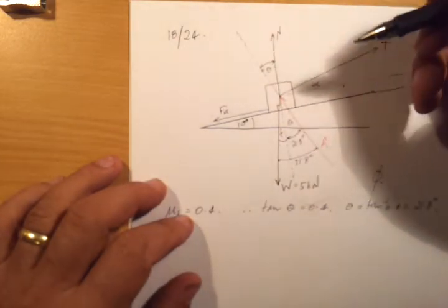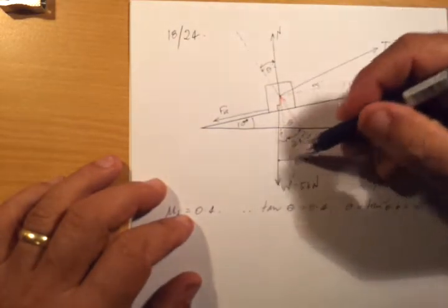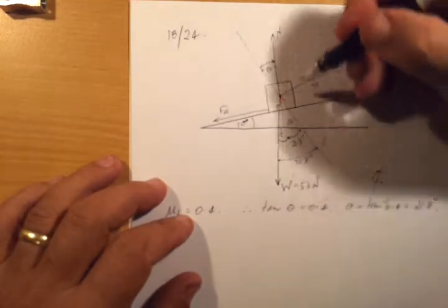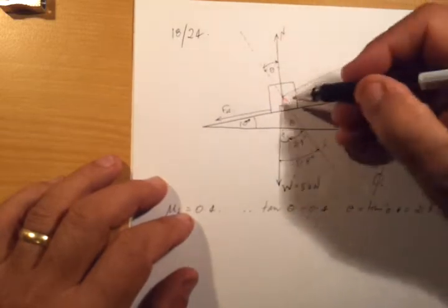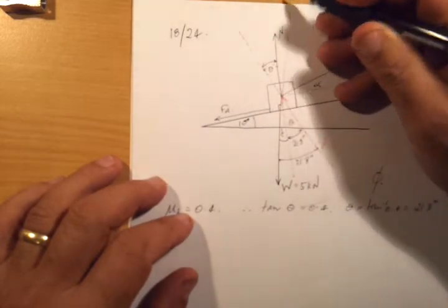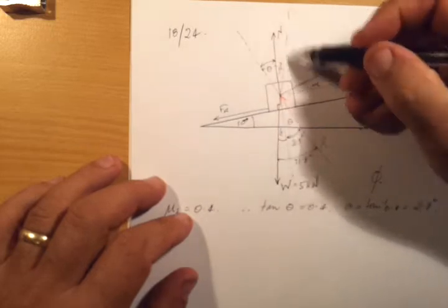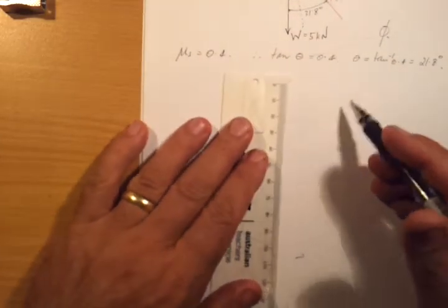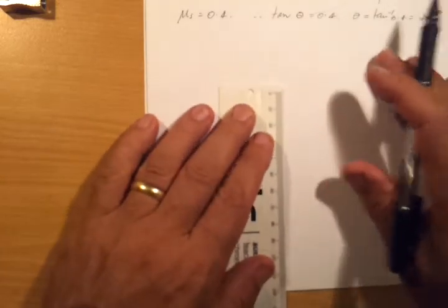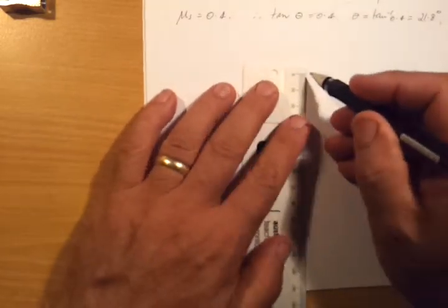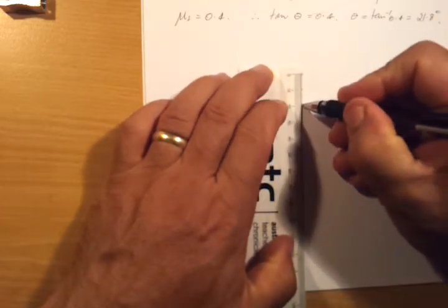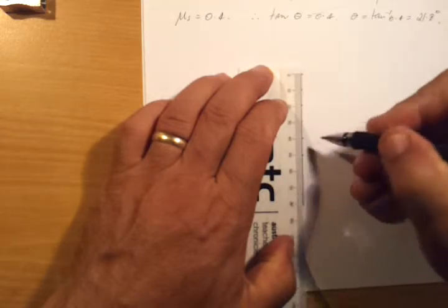Okay, so if we know that this angle to the vertical, between R and the vertical, is 31.8 degrees, and remember that of course the normal is not going to be vertical, there will be a 10 degrees gap here. Then we can start to work out a simple graphical solution to this problem. And to do that we'll use a ruler, we'll create a vertical line, and I'm going to use a scale of 10 millimeters as 1 kilonewton. So there's 5 kilonewtons.